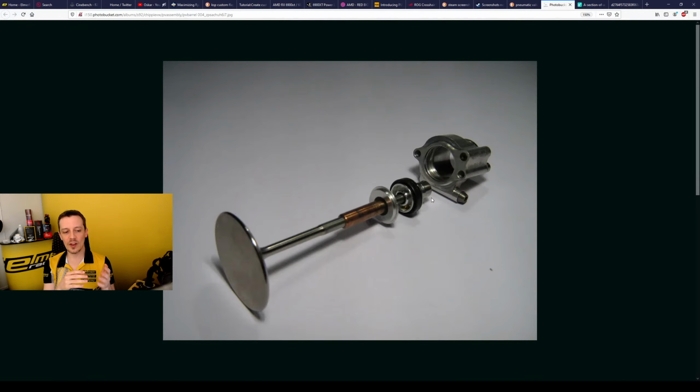This could potentially be very good for hypercars or something like this, where you want extremely high RPM capability, but you still want to be able to potentially do 100,000 or 200,000, 500,000 kilometers on an engine. You would be able to do that with a pneumatic valve system if you have a really good setup for that. Preferably also so that your control components don't end up being clogged by deposits eventually. But it is a really good system that has a lot of potential.